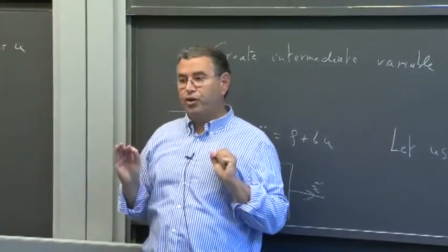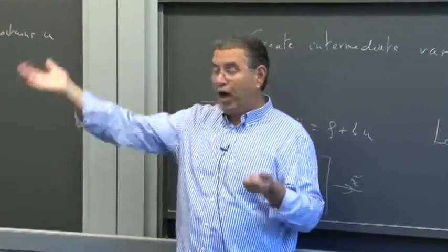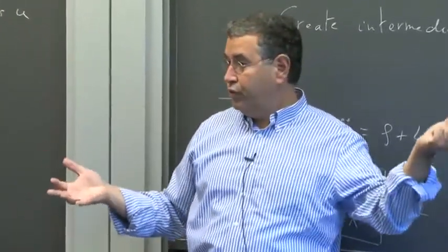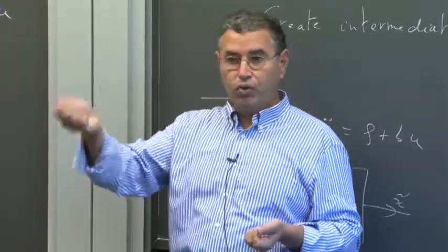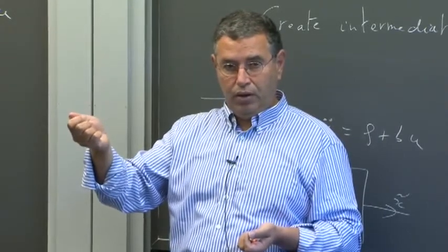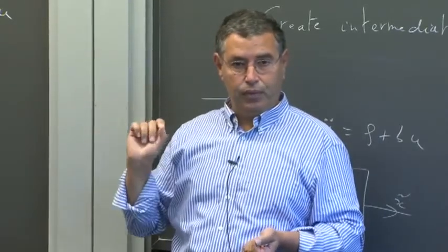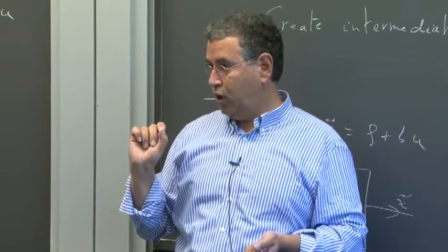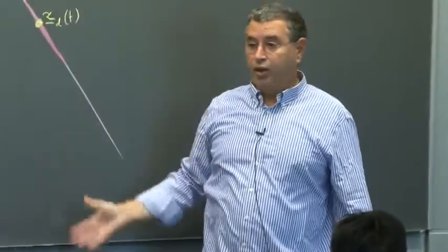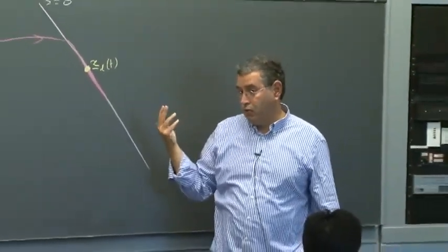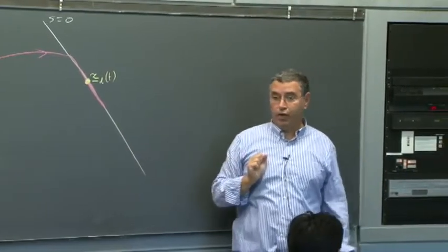The geometric interpretation is that S equals 0 is a hyperplane, but also because of its definition, it's a dynamics. And therefore, once we know we stay on this hyperplane, we know exactly what happens to the trajectory. Replacing an nth order problem by a first order problem also says once you're on this hyperplane, it takes care of itself. Basically, the motion is entirely defined. Questions about that?